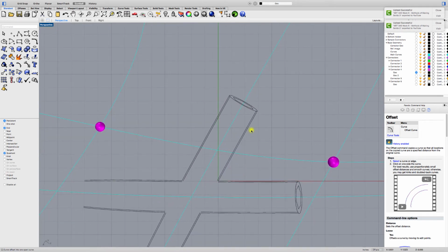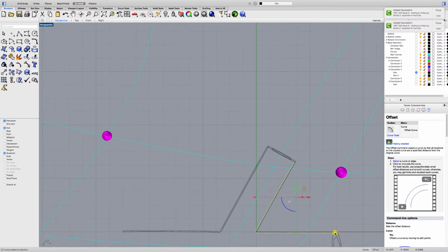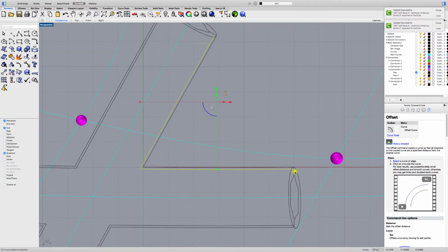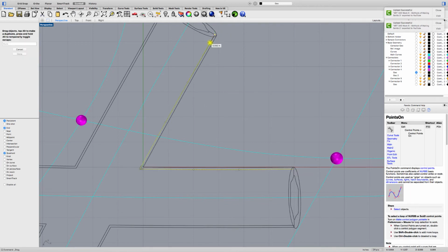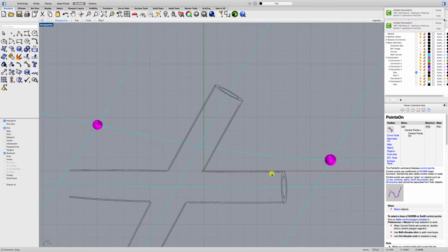But what I want to do up here is I want to move these endpoints down. Because you can even see here, if I try to extrude this straight or perpendicular to the plane, I might not be able to get super far because this surface right here is going to go past that surface, and it might create some issues editing. So what I can do is I can chop it, I can cut it. Why don't I just see if I can just move some control points down just a little bit. And I might do that for the other ones as well. Why not? It'll take a quick second.